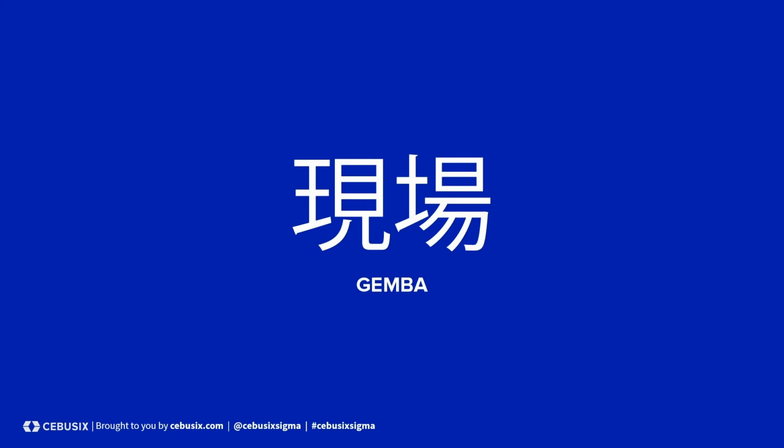Part of reducing waste is reducing motion, and that requires everything and everyone to be as close to the actual place the work is being done as physically possible. The term Gemba literally means the actual place. In lean manufacturing, Gemba is the place where problems are most visible and where improvement ideas should initiate. In quality management, Gemba literally means the production floor and asserts that when a problem occurs, the only way to solve that problem is to go right to the source to gather data and develop solutions. We should take a step back from the day-to-day operations and take a Gemba walk in order to identify wasteful activities.